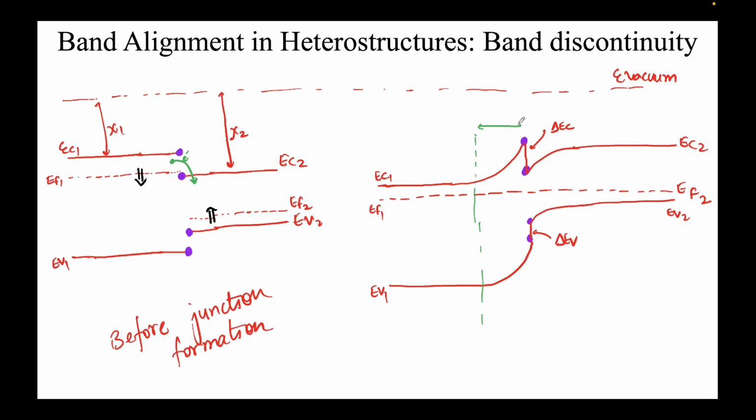This is your depletion region. Call this WN, because this is on the N side. Correspondingly, this is your depletion region on the P side. Call this WP, measuring everything from the metallurgical junction. If you draw a vertical line joining these orange points, purple points, you'll get the straight line, which is what I have drawn here.